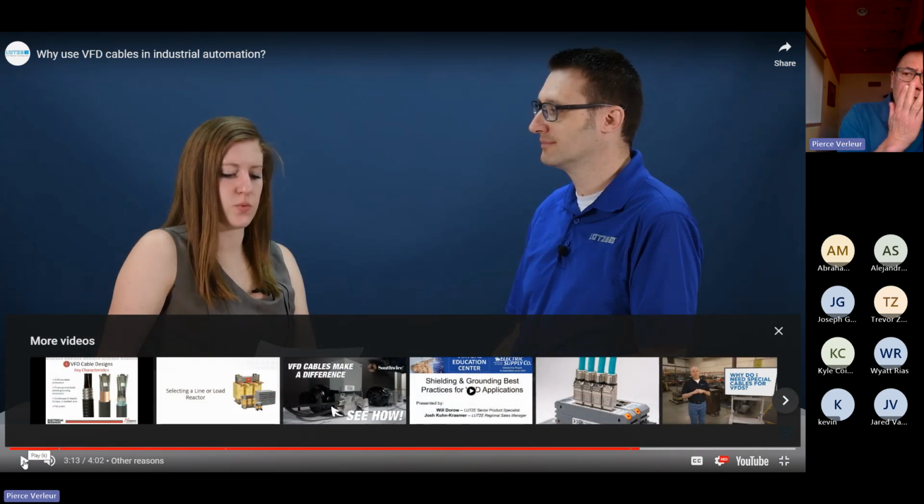This is very interesting. Do you have any other reasons? I want to make a clarification here. PVC is still great for the jacket of the cable. What he's talking about is the individual wrap on each conductor. They've gone to cross-linked polyethylene, XLPE. That material, an insulator, versus PVC, also an insulator, allows the cable to be designed such that it has a much lower capacitance in the cable itself. We don't want capacitance in the cable. So XLPE versus PVC, but PVC is fine to use on the outer jacket.